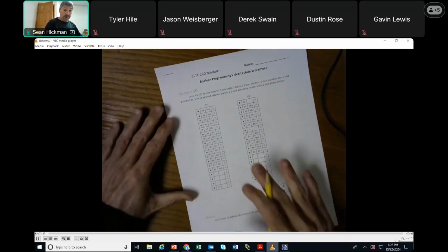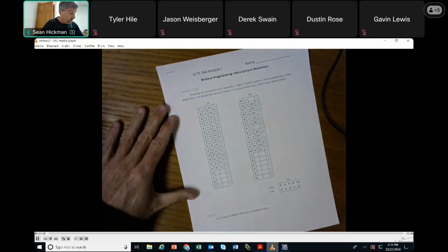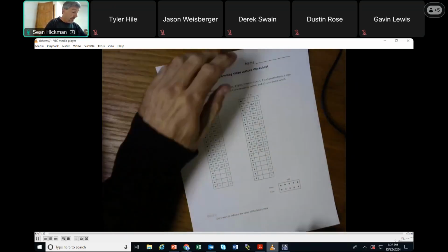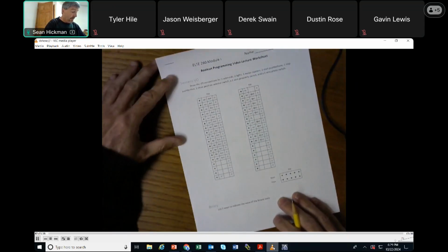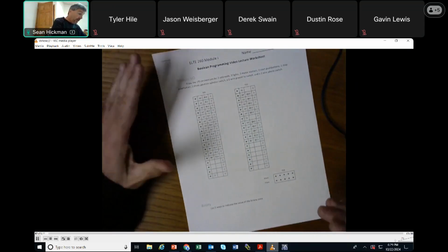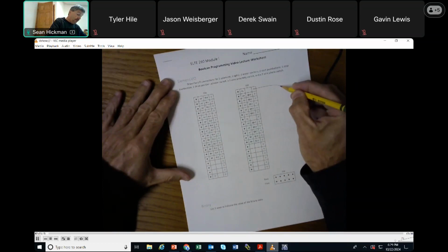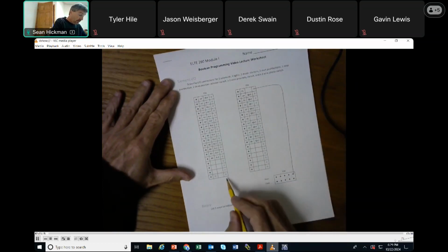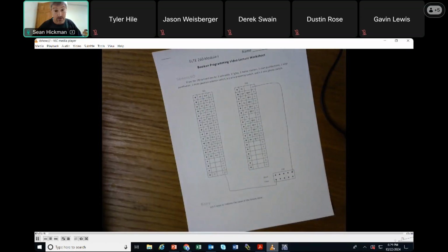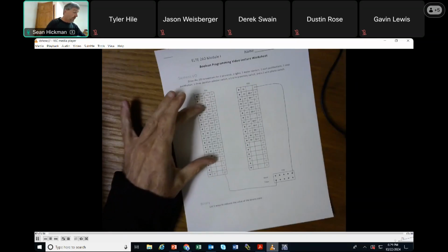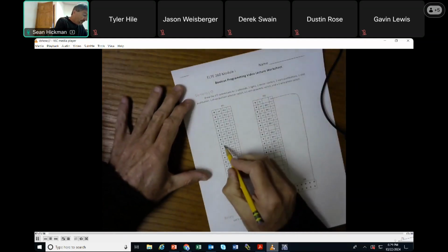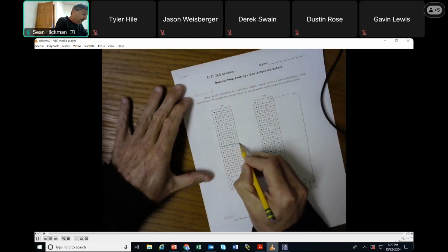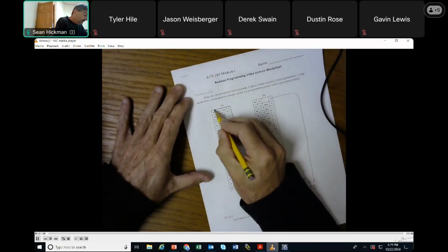We're going to take a look at our wiring right here. Here's the wiring harness for this. And it's similar, we get our freebies where we can run the voltage here and we can run the ground here. Okay, source and sink the output modules. All right. But now when we look at the input modules, you see that the first byte is right here.